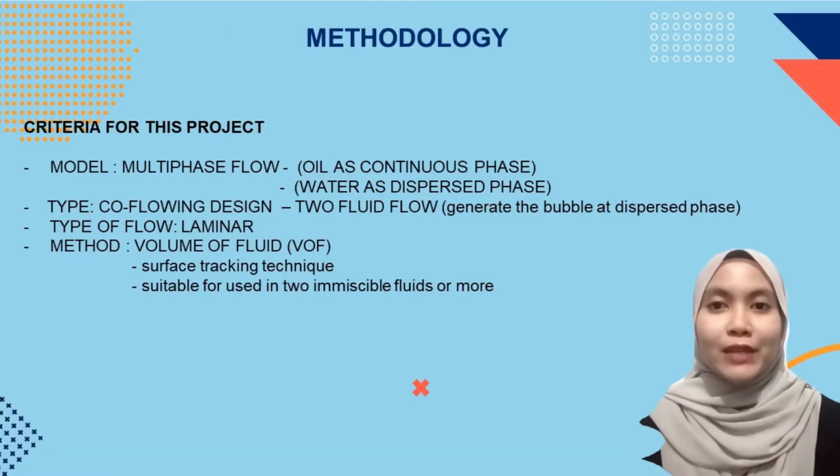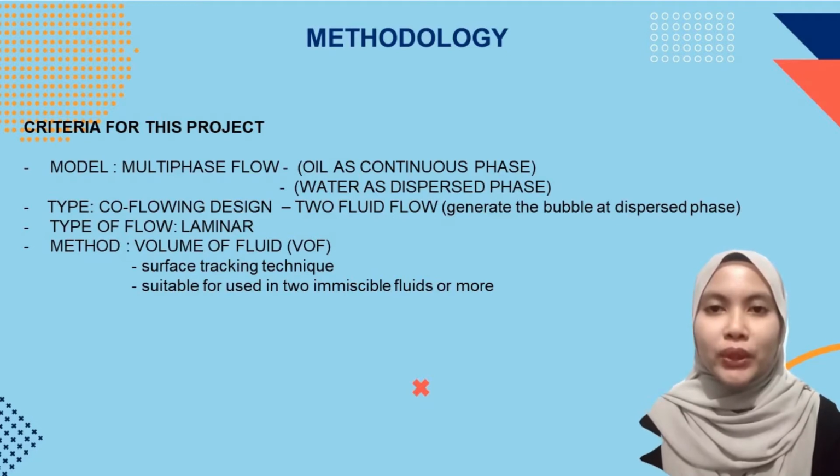In order to make the simulation in this project, the methodology needs to be great to know the steps of the project. So, the criteria of this project: the model uses multi-phase flow, which contains immiscible phases that use oil as the continuous phase and water as the disperse phase. The type of geometry is co-flowing geometry, which can hold two fluid flows in one channel but is divided into two channels, outer and inner.